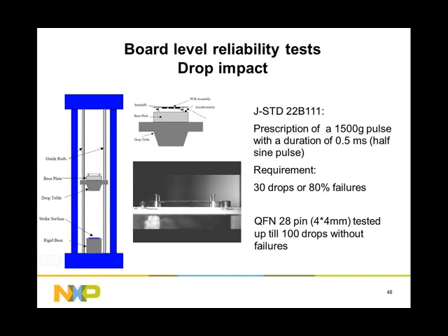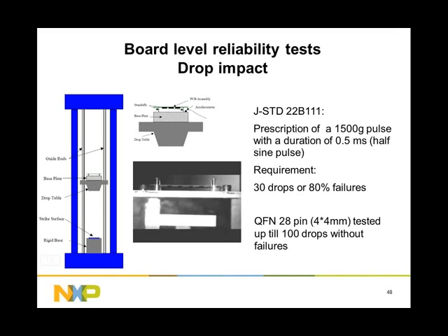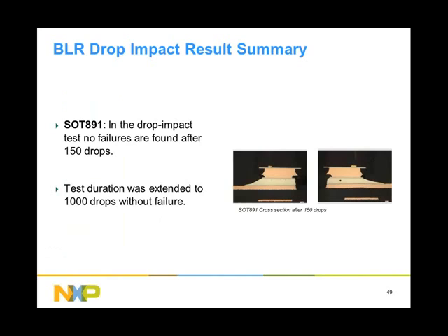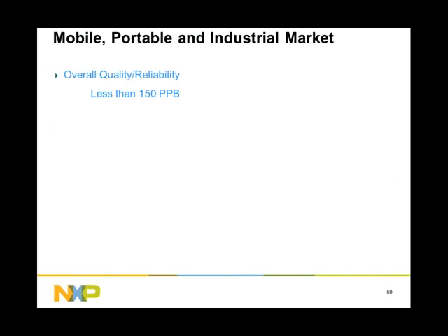And the JEDEC requirement is that the device can withstand 30 drops, and we performed 150 drops for the SOT 891, so this is the 6-lead MicroPak, without any failures. We continued to do this testing until we got to 1,000 drops, and still there were no failures for the MicroPak packages.